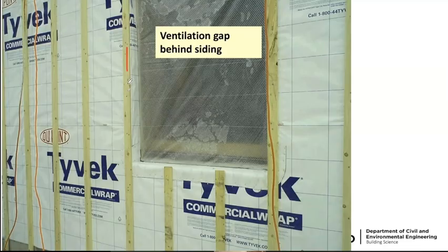Now, hydrostatic pressure won't build up because as soon as water goes through the cladding, whatever it is that's being attached here, the water will just fall right down. It'll just fall under the force of gravity. There will be no gravity pressures to drive the water in.